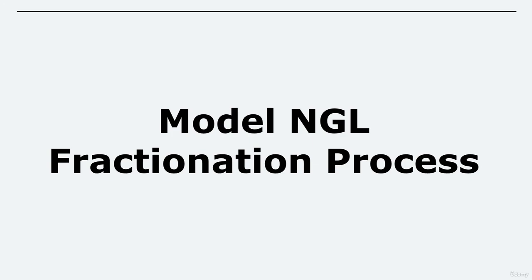Model natural gas liquid fractionation process. In this video, you will use the column input expert and column property view menus to define and configure the standard HYSYS column models. You will also learn how to review and interpret various outputs and results from these column